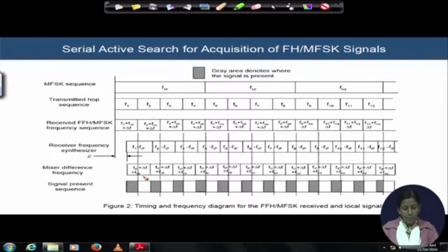In this, we have an assumption that it is 4 times. Remember, the 4 times is the hopping frequency than the incoming frequency. Assumption number 2, we have a Doppler contributed by del F, Doppler frequency, and we have a timing error attributed by epsilon, and hence we understand that the frequency previous to this point of our interest, and the frequency at the next instant, both will be different than the current hopping frequency.